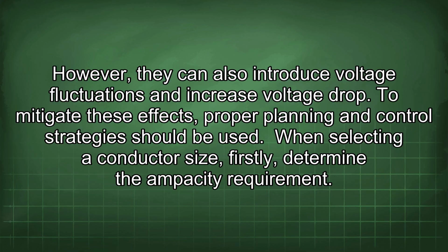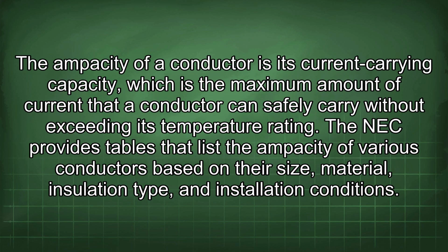When selecting a conductor size, firstly determine the ampacity requirement. The ampacity of a conductor is its current carrying capacity, which is the maximum amount of current that a conductor can safely carry without exceeding its temperature rating.